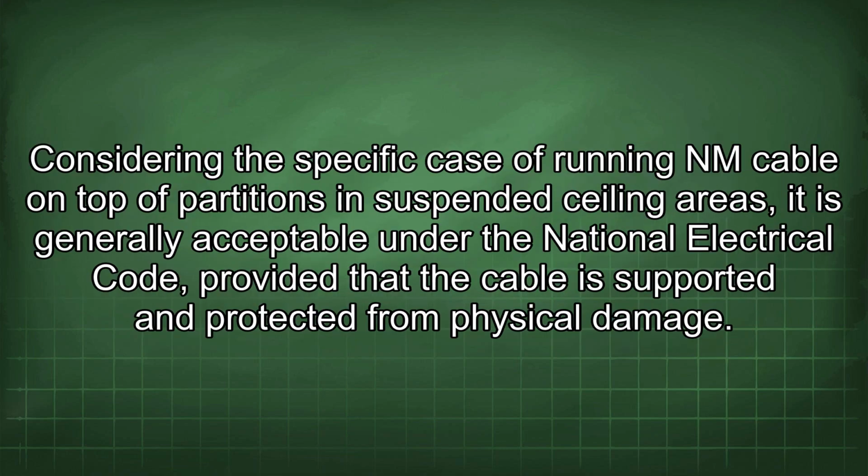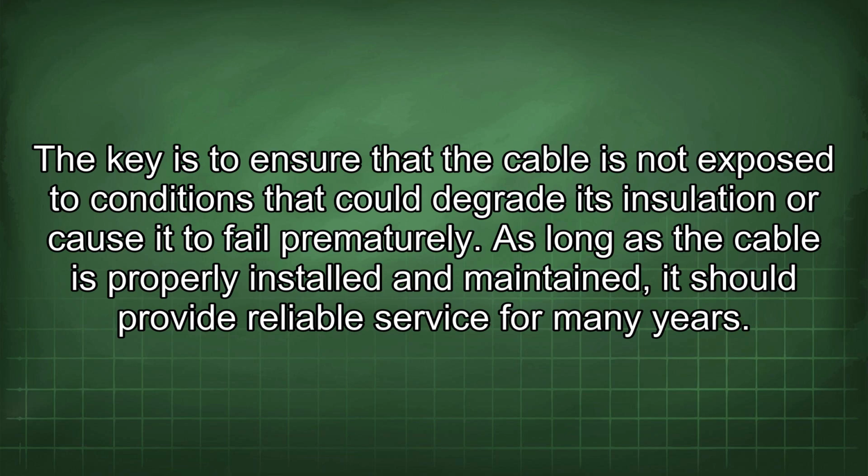Considering the specific case of running NM cable on top of partitions in suspended ceiling areas, it is generally acceptable under the National Electrical Code, provided that the cable is supported and protected from physical damage. The key is to ensure that the cable is not exposed to conditions that could degrade its insulation or cause it to fail prematurely. As long as the cable is properly installed and maintained, it should provide reliable service for many years.